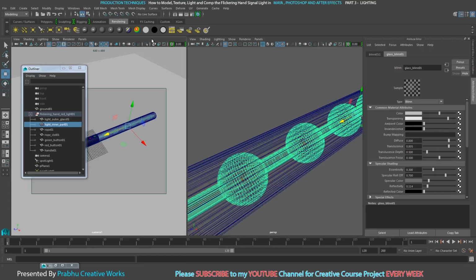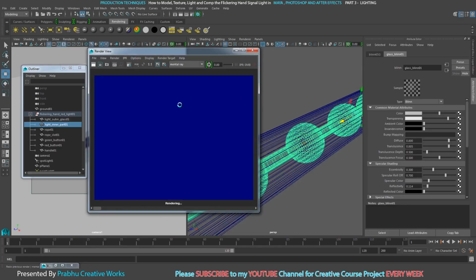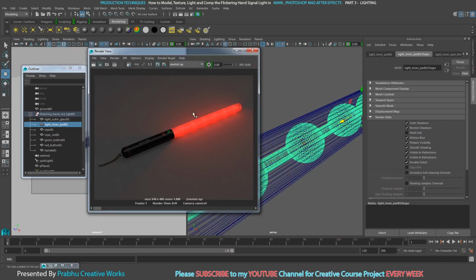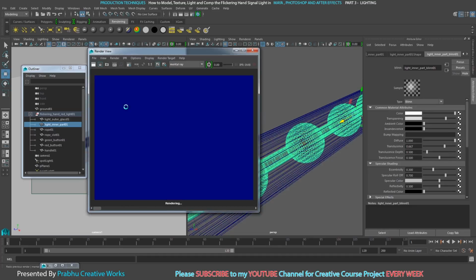Now select this one, keep this image for comparison and click the render button again. See here, it does not look real. So I will select this object and reduce my transparency level very low. I will reduce my translucence amount very low, and click render again.